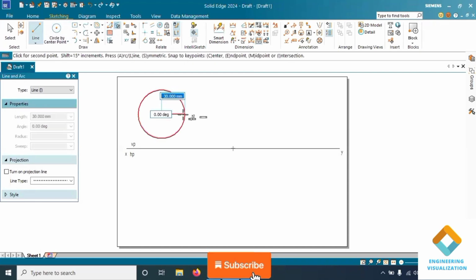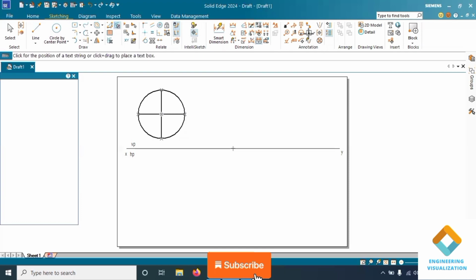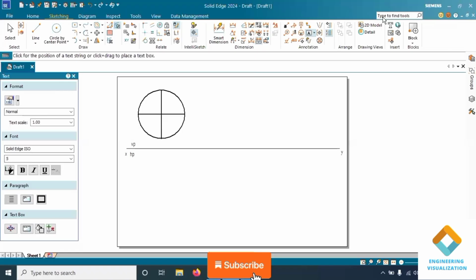Here I'll be constructing a circle using the center method. So for the diameter we will take directly the major axis dimension here. So in the question the major axis is given as 60 mm, that means we'll take the same diameter, that is 60. Enter.